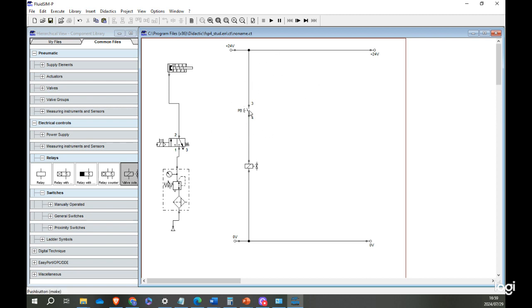What should happen is that when we press our push button here, our cylinder should extend, and when we release, it should retract. So let us click start. As you can see, the dark blue air wants to go into the cylinder to extend it, but it can't because this is a normally closed two-way solenoid valve. How we allow the air to pass is through the push button. If you press it, nothing is happening. Why? Because your solenoid valve is not communicating with your two-way solenoid valve. I did that on purpose.